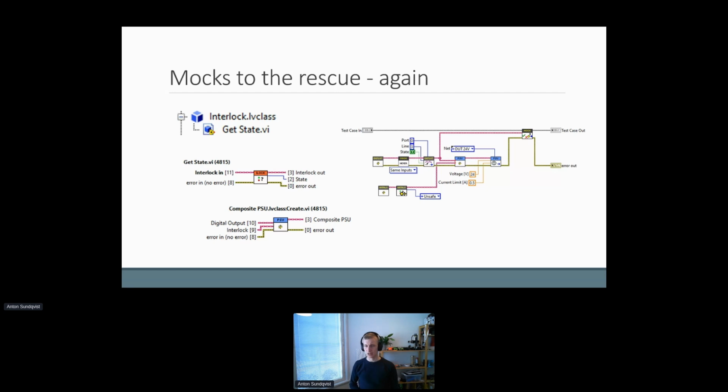And now this would look like this, and I will walk this through bit by bit here. So the higher row here, or the first row there, is actually pretty similar to what we had before, except that now the expectation here says never. It doesn't say one anymore. Earlier it said that we expect one call to this VI. Now it says that we are never supposed to get a call to this VI with these inputs during this test.